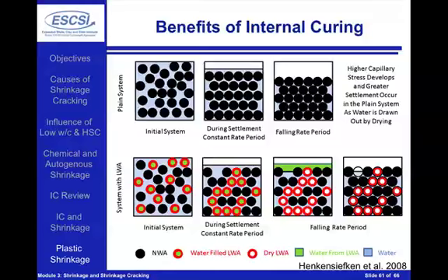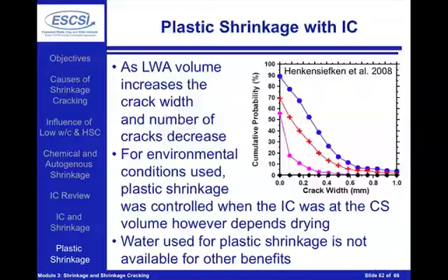On the bottom, we see a system where internal curing is used, shown as a water-filled lightweight aggregate as the red dot with the green center, which is the water from the lightweight aggregate. And as the system consolidates, water can come out of the lightweight aggregate, relieving this pressure and essentially providing more water that's available inside of the system. Until you started to evaporate or until you started to pull all the water out of the lightweight aggregate, you don't really reach that falling rate period where the stresses would be high and would start to cause the potential for cracking. So the whole idea here is you could use that water at very early ages.